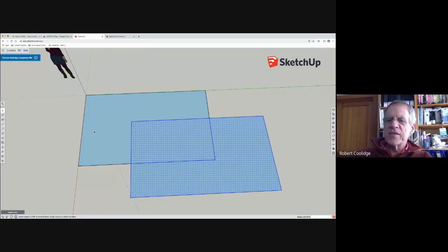The one lesson you must learn about SketchUp is that the onus is on you to make things into separate things. You have to make groups. Everything you do must be part of a group or component in the end. Otherwise, you end up with a giant gluey mess of everything stuck together because of this automatic feature.